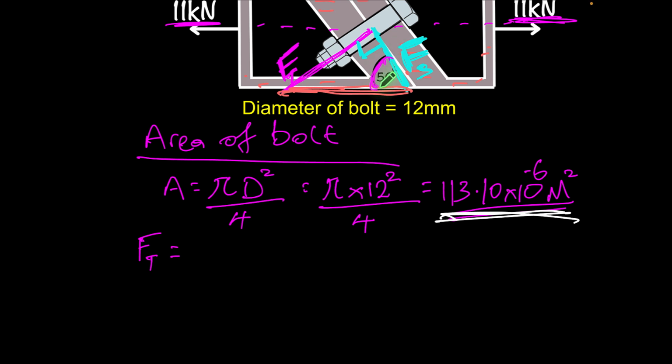So we're going to use the opposite side for Ft and the hypotenuse side, which is representing the 11 kilonewtons. So this is what we'll have then for that unknown Ft side. It's just going to be force sin angle, just as we've done before with force components.